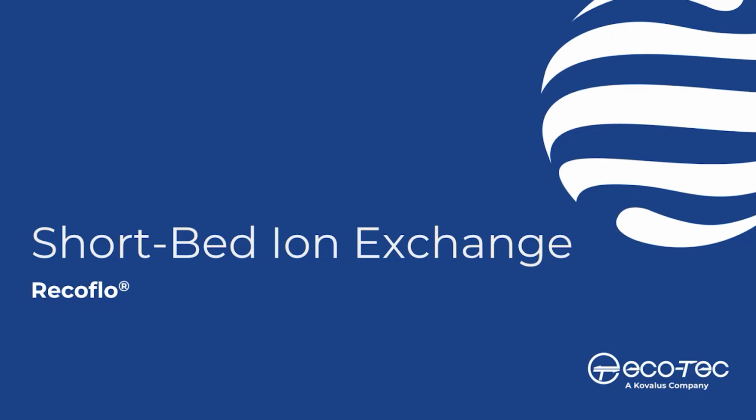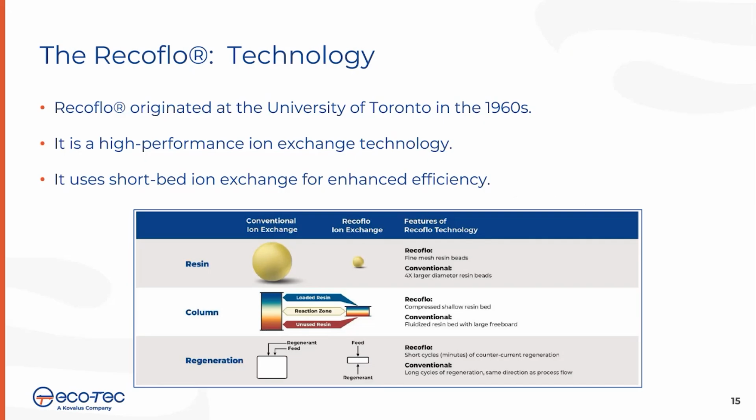Now that we are aligned on ion exchange basics, let's move to the core mechanism behind our approach, Recoflo short bed ion exchange. Recoflo originated at the University of Toronto in the 1960s. On Recoflo, the resin bead is much smaller, on the order of about 20% of the diameter of a conventional